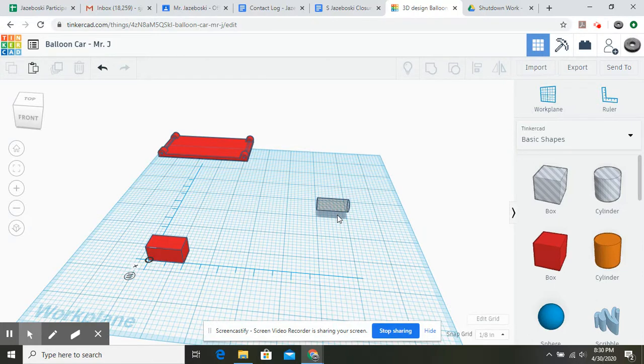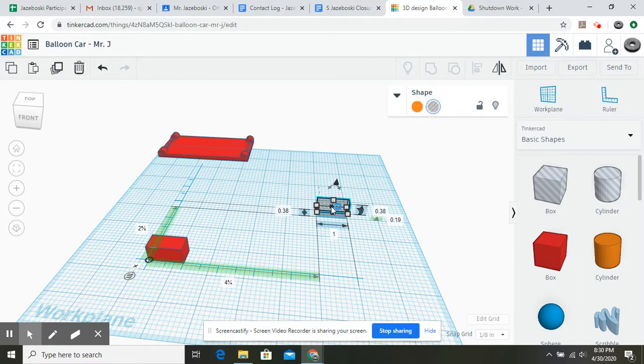Then we're going to position this. But before we position this into the block, we're going to change this to midpoints. We've used this before. If we go down here to the circle with the 3 lines in it, you'll see it lights up red and it says use midpoints. Once again, this is endpoints. It lines up with the corner, the X and the Y axis. We're going to go to use midpoints, and now it's halfway through the center of each of those.